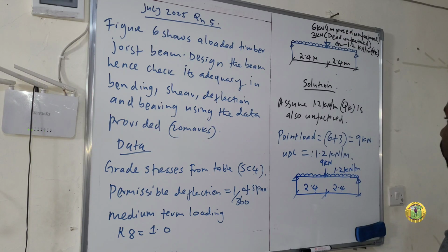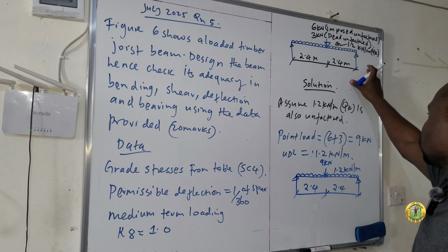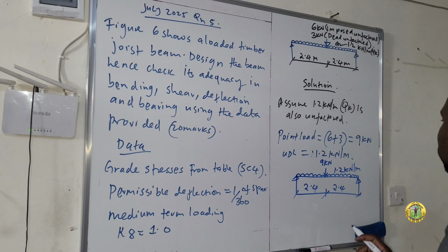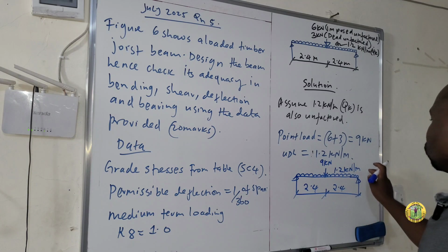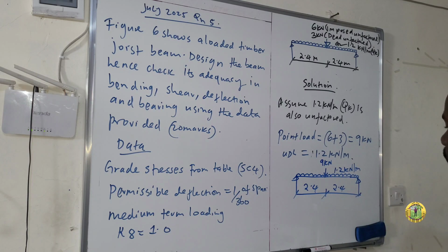But because of the philosophy behind the design of timber to BS5268, it uses the permissible stress, so you are not supposed to factor the loading. Just use the way they are. They may test you in various aspects, as you have seen in the question.